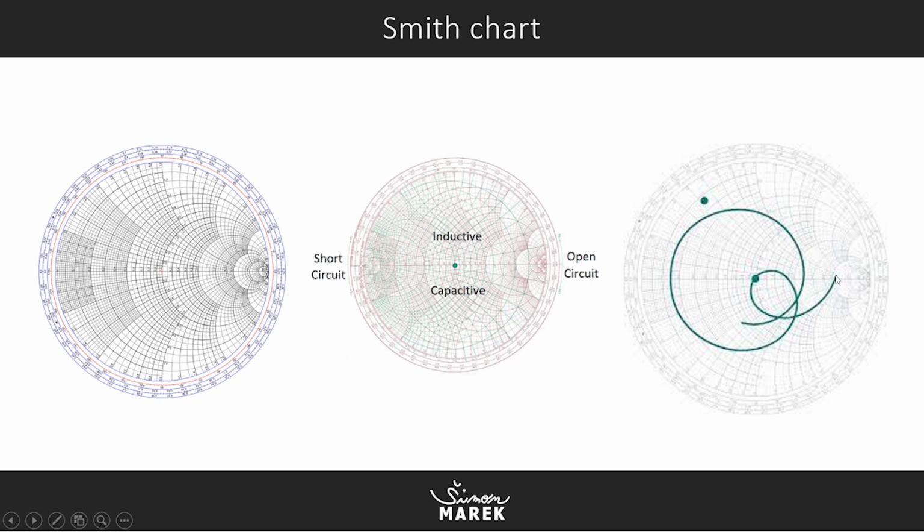the final measuring profile looks like this, which is a line with frequency sweep, and there's a frequency of let's say 100 megahertz, and it ends at 10 gigahertz, and there's the whole trace of how our device behaves across different frequencies.